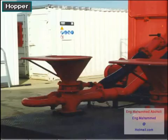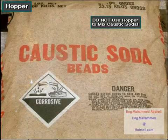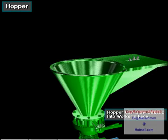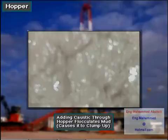A hopper is like a big funnel. Crew members put sacks of mud material into it. They do not, however, use the hopper to mix caustic soda. The hopper can blow dry caustic back into the face of the worker mixing it. In addition to being dangerous, adding caustic through the hopper can flocculate the mud, cause it to clump up.